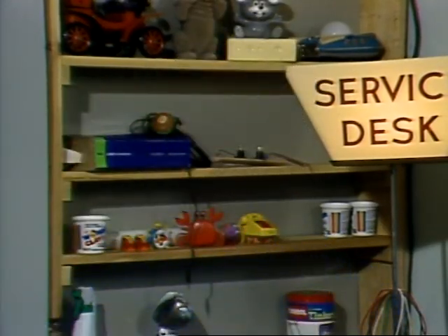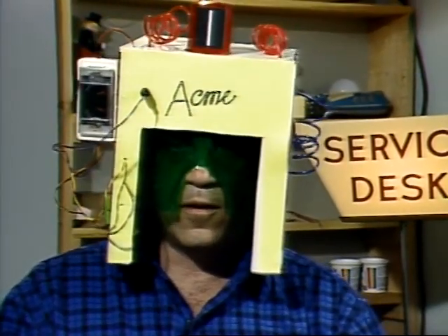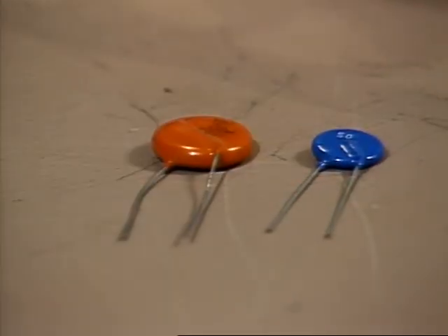Is everybody waiting for me to mention the surge protector? Okay, I mentioned it. The surge protected multiple outlet is a lot like this Acme falling elephant protector. Since I've been wearing it, I haven't been troubled by falling elephants. The surge protector is a component called a metal oxide varistor, MOV for short. It works by being voltage sensitive. As the voltage rises, it lowers its resistance. Under normal conditions, the MOV does very little. If, say, lightning induces an abrupt spike of higher voltage on the line, the MOV shorts it out.